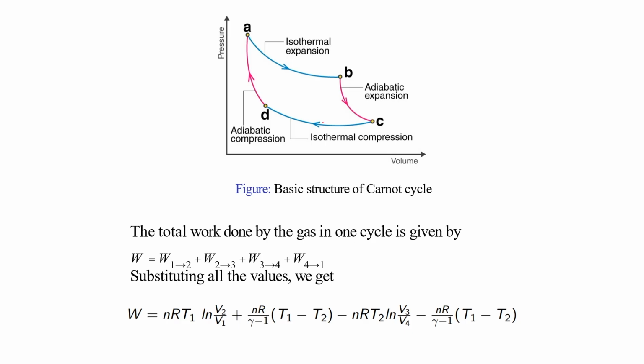Then isothermal compression, between point C and point D, where you get the same temperature value. We started with temperature TH here, and here also the temperature is TH, but here the temperature is TL, and at this point it is also TL. This is the isothermal process at TL, and from TL it goes to TH. So again isothermal compression, volume decreases, and in the adiabatic compression the volume also decreases.